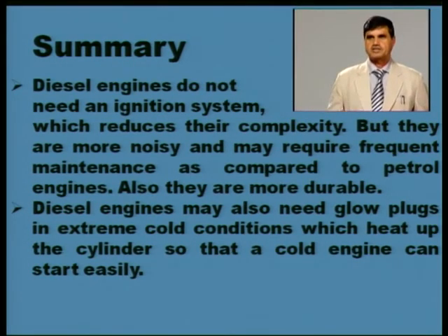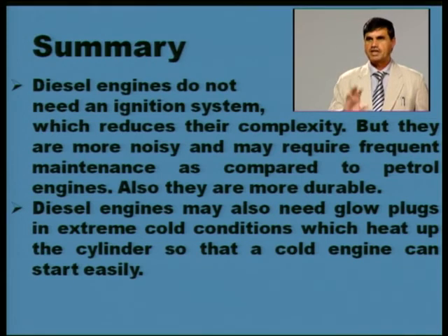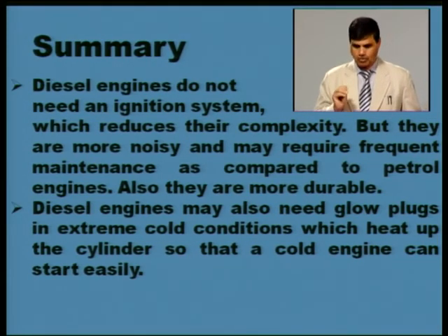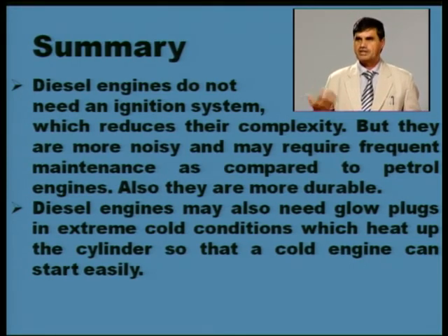And no separate ignition system is needed in the case of diesel engine, whereas in the case of petrol engine we are having spark plug, ignition coil, capacitors, separate battery, ignition switch, everything will have to have. So cost wise, if you are comparing, petrol engines become more costlier because many additional components will have to be added for starting the combustion. In the case of diesel engine, the combustion is just after compression, it is very easy also.